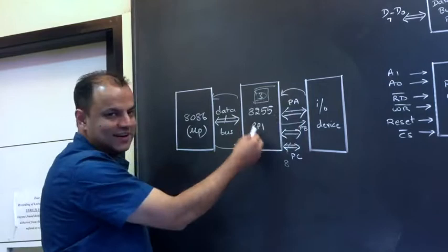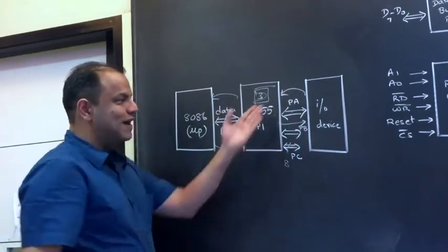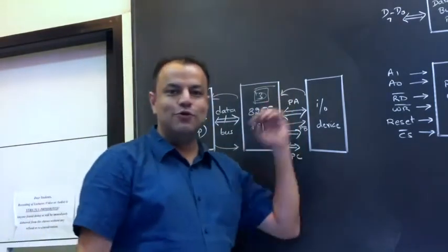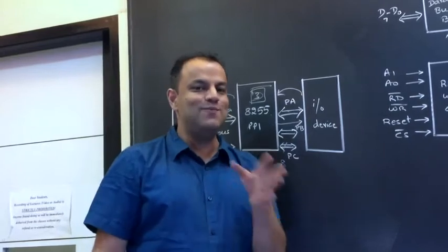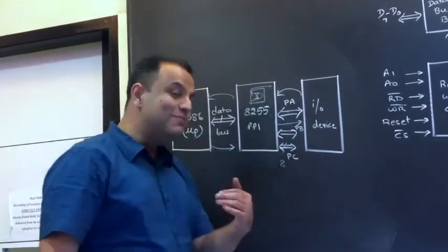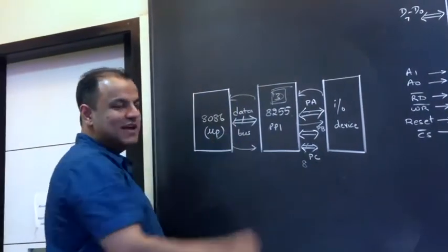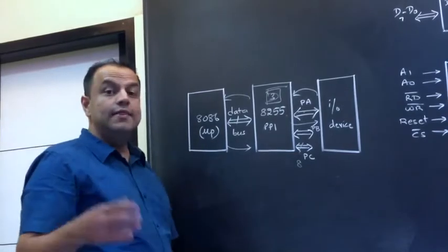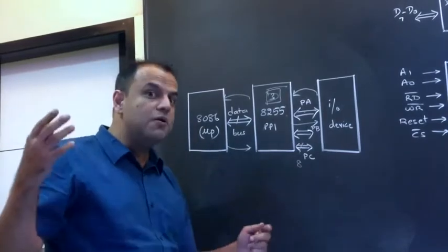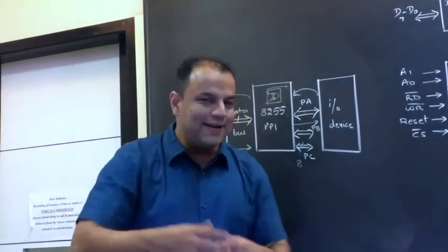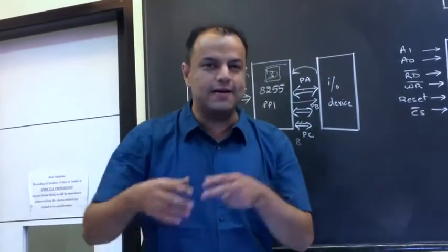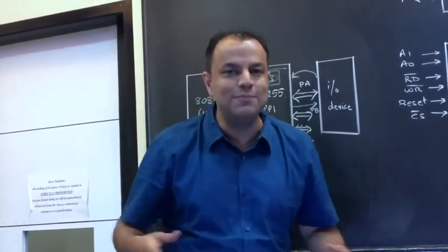Because before sending the next number also, the I/O device will have to, yes, you got it, again ask for permission. This time will 8255 give permission? No. When will it give permission? Only after 3 has been transferred to the processor. Can that take time? Yes. Can that take a long time? Yes. 8255 doesn't care about time because it doesn't know time.